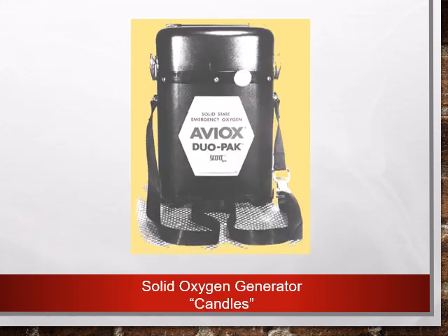Solid oxygen candles have an almost unlimited shelf life and do not require any special storage conditions. They are relatively inexpensive and lightweight. They are ignited either electrically or by a mechanical igniter. They cannot be tested without being used. They generate heat whenever they are used. So, they must be installed so that the heat can be dissipated without damaging the aircraft structure.